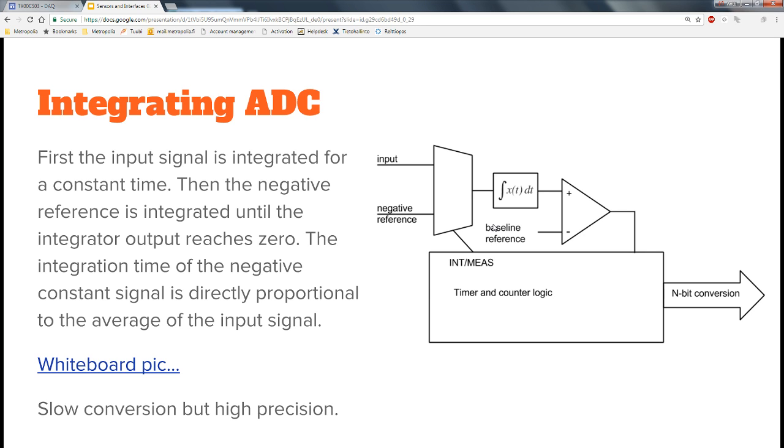So fundamentally what this one does, it has an analog integrator. Have you studied the operational amplifiers? Okay, but anyways, with operational amplifiers, one of the basic circuits is an integrator, which simply gets the signal as a current signal and uses a capacitor to have the integral of the input signal on the integrator output.